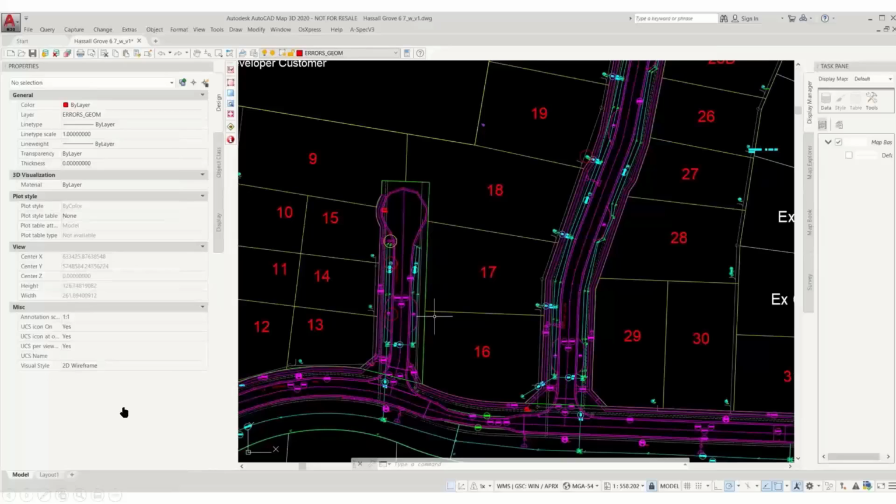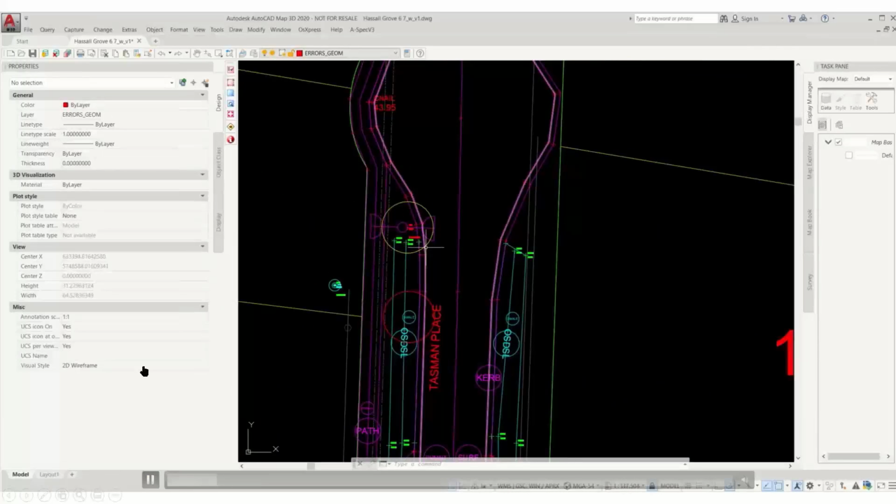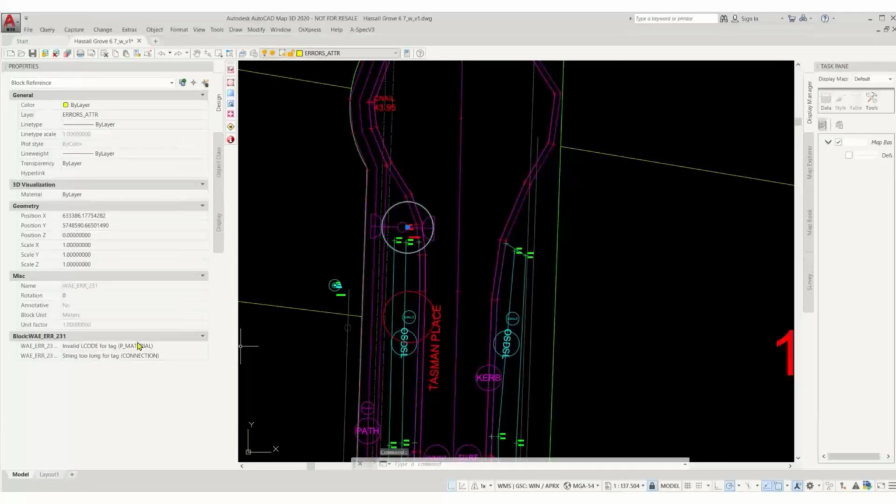And so if we open that error file, this is the same CAD drawing, the way that hydrant was put in, and we can go and look at the errors. They've been marked with circles. So this is essential, because now people, and I'll actually pause this one right there, because that circle, there are different colored circles for attribute and geometric errors. But this says, look, the domain value for pipe material on that particular one is wrong. It doesn't match what's going to go in the GIS. This is huge. Or there's data that's too long for what's going to be put into the model.